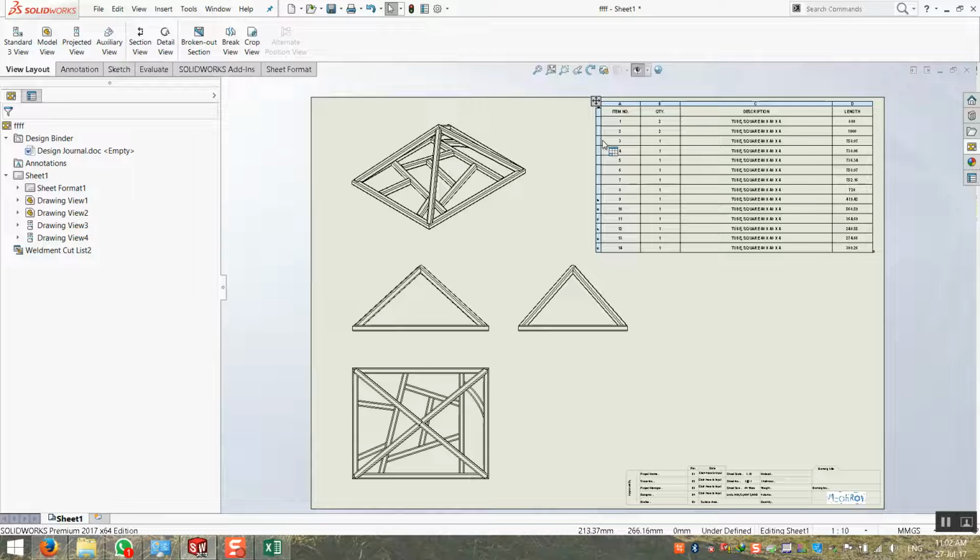And from here the operator can know that you need a through hole. Yes, you identify the position of the hole from center to here or from center to here, and it will be identified in this view. But does the hole have a specific depth or is it through? When you make this, we express to him that I need this through. If not through, you will specify for him the depth.